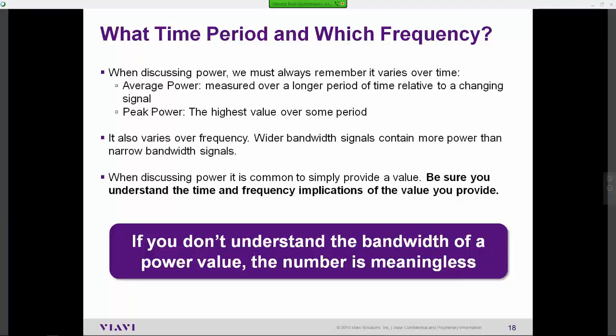The reason why is that if they do have an interferer out there that may be intermittent, they don't want that signal strength averaged into all the other samples that were taken. They actually want to collect all the peaks. Because when you collect all those peaks, oftentimes the signature becomes much more prevalent or obvious that, yes, there is a problem within the spectrum, because you didn't average it in with all the other signal strengths within that same part of the spectrum.